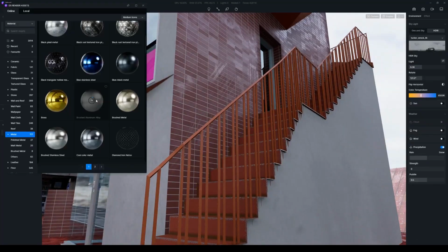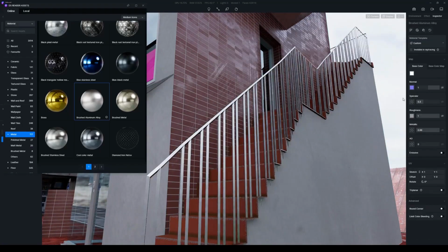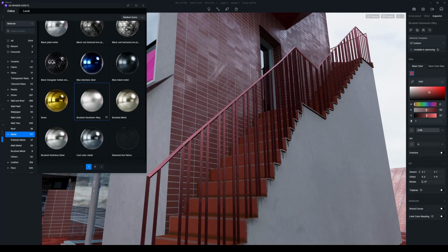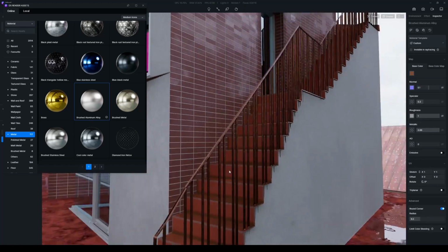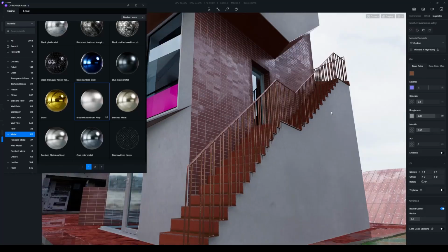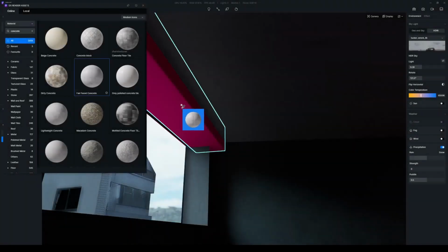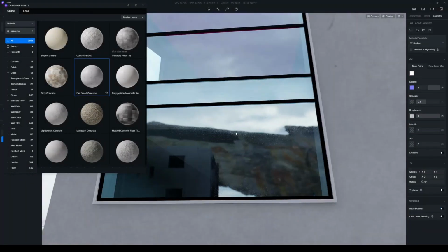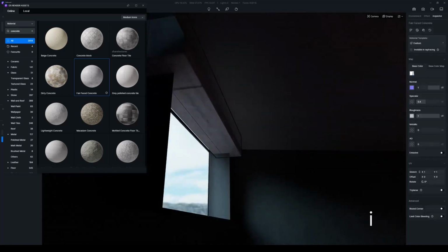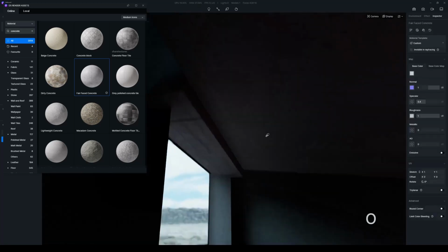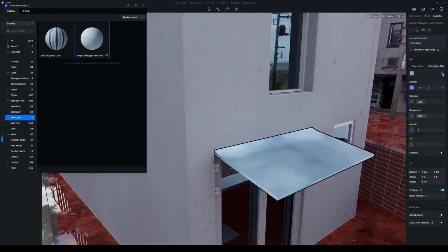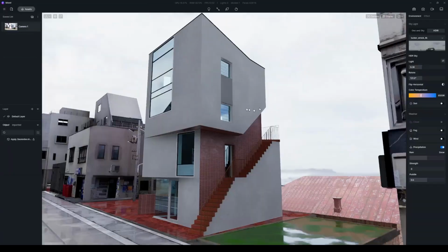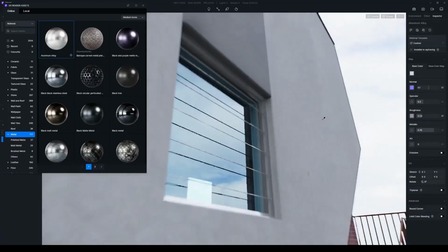For the building's handrail, I'll still use a metal material from the D5 Asset Library and adjust its color to a brownish red. Again, one-click round corner. This is a very handy tool in D5. Another tip is that after adjusting a material from the D5 Asset Library properly, you can use the shortcut key I to copy it, and shortcut key O to paste it on other surfaces to save time. Material adjustment reveals the details, so here I'll continue with other parts of the scene.